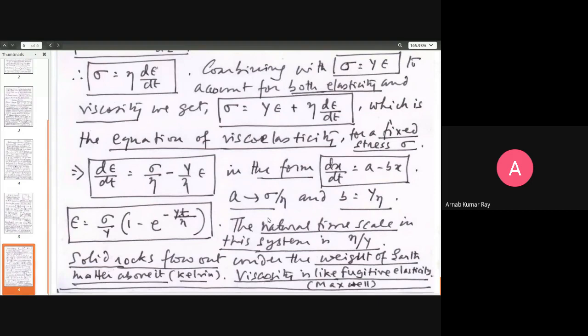If you keep the drum turned over for a long enough time, on the time scale of days, then slowly, regardless of what the temperature is, if the temperature is cold, then the movement will be very slow. Slowly, you will see that the tar material is coming out and gathering around the mouth of the overturned drum. In the summer, when temperatures are higher, this property will be more visible. In the winter, it will behave almost like a solid. You wouldn't be able to tell on your time scale of observation that it actually has liquid behavior. So that is an example of a viscoelastic material.